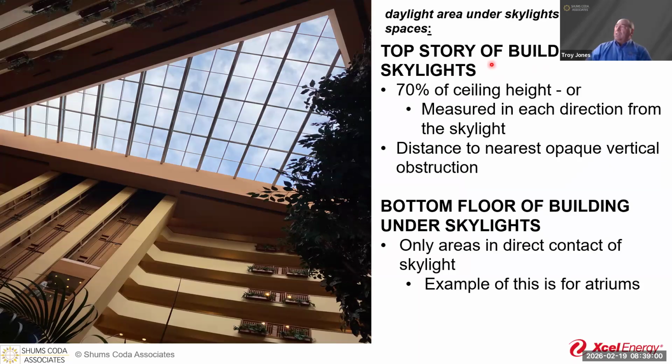So on this, the multi-story spaces, 70% of the ceiling height measured in each direction from the skylight. Remember I said with triangular, we're going to take it this way, this way, and that way. So it's perpendicular off of those.